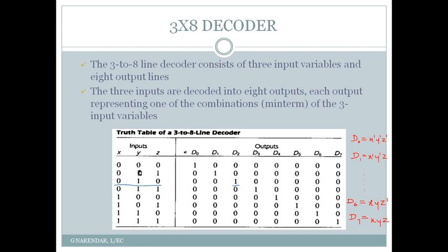And in particular we started looking at the working of the 3 by 8 decoder, and we defined what a 3 by 8 decoder is, and we have shown how the 3 by 8 decoder is formed by using a simple truth table consisting of the inputs for the 3 bits that are applied at its input and the 8 outputs that are available for the decoder.